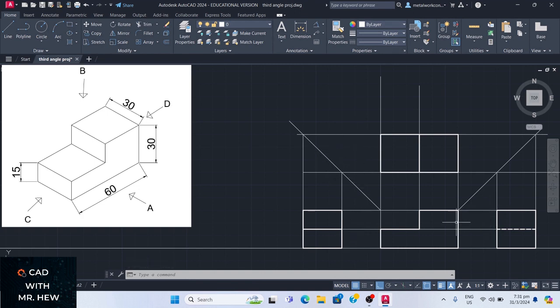All right, now I'm going to label the drawing, right? So I'm going to use a text command, so write text. I'm going to specify the starting position. 4 millimeters is a better height. Rotation angle, enter 0. I'm going to type with caps lock on. So we say front elevation. Then we're going to go up to the plan up here. So we're going to label plan.